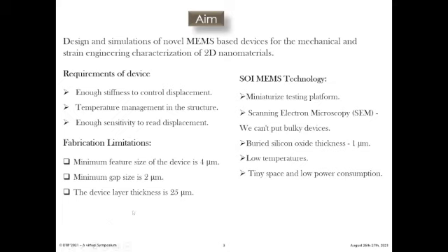The requirements of our device are having enough stiffness to control the displacement and the temperature management in the structure, and enough sensitivity to read the displacement at the sample. So we are going to use SOI MEMS technology, which has different advantages, like a miniaturized testing platform, which can easily be put into a STEM for inspection. And we have a buried silicon oxide thickness of around 1 micrometer, and it operates at low temperatures. Also, it occupies just a tiny space and requires low power.